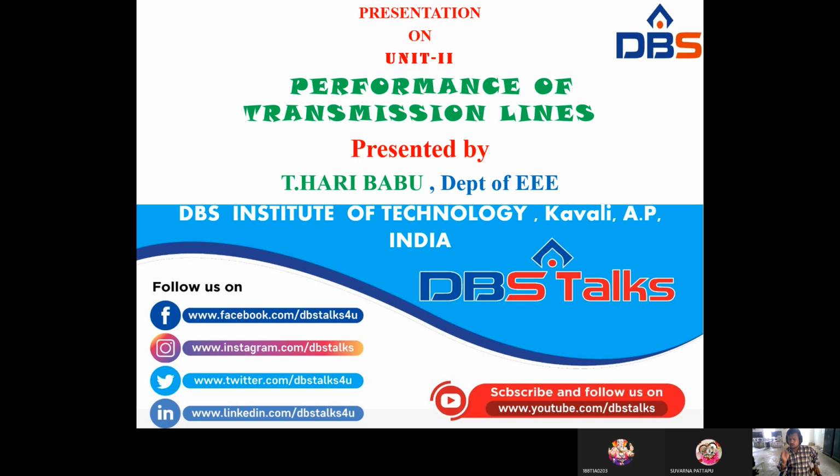A equal to D equal to 1 plus YZ/2. These A, D values are not changed even though it is a Nominal-T or Nominal-π. Just remember. Then B is equal to Z into 1 plus YZ/4, and C is equal to Y for Nominal-T. Right? And we have to apply the symmetry and reciprocity conditions. Both are applicable. Then go for the Nominal-π.